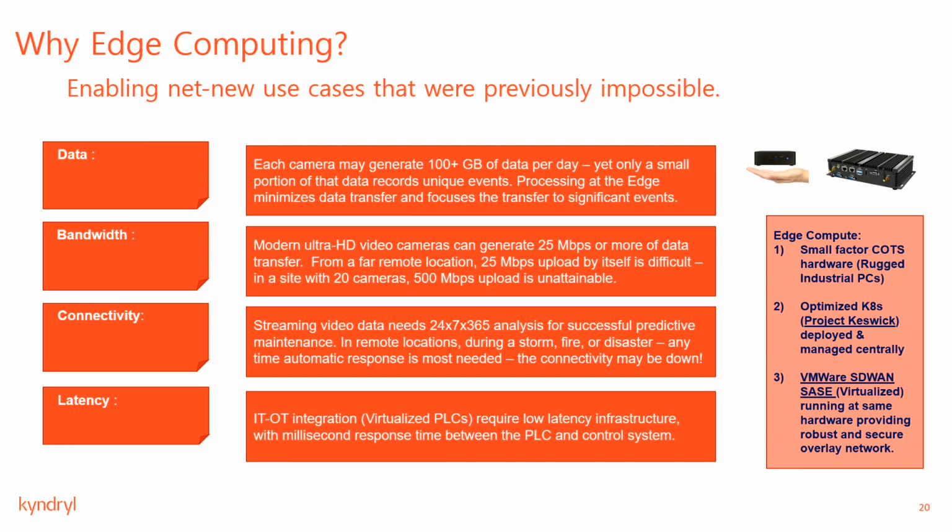But by using a camera, we're now capturing that entire component, right? What if you had the thermistor here, but the thing that was getting hot was just here, 30 centimeters away? You've missed that opportunity for failure detection, whereas with imaging, you're capturing the entire element.